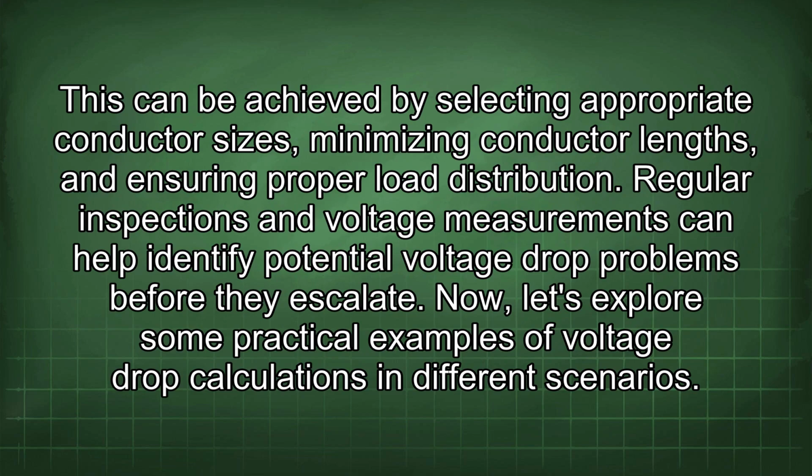This can be achieved by selecting appropriate conductor sizes, minimizing conductor lengths, and ensuring proper load distribution. Regular inspections and voltage measurements can help identify potential voltage drop problems before they escalate. Now let's explore some practical examples of voltage drop calculations in different scenarios.